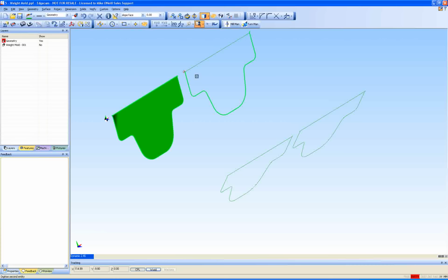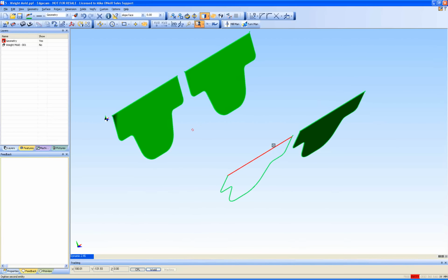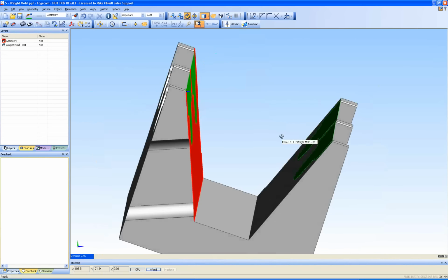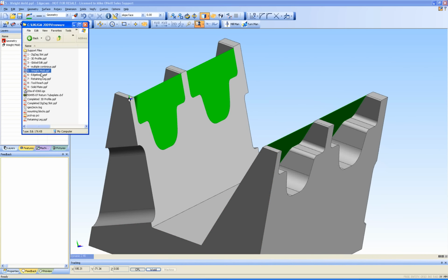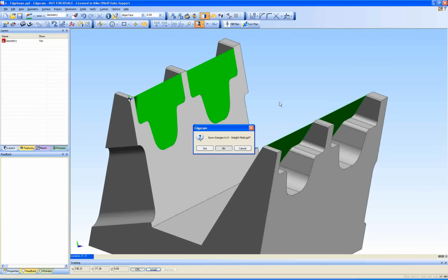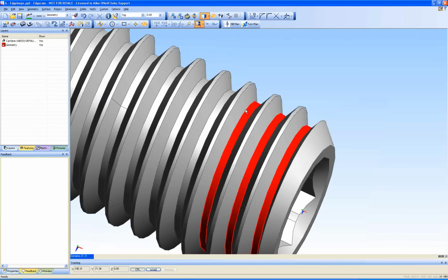So it's just a little bit of a time saving rule really. And then the ruled surface again doesn't have to be precisely accurate in this particular case, but it certainly is a perfect solution to box in the sides of that particular component in order to drive a cutter along. So again, a number of tips and tricks in there, supported also with the freeware function. Another item that is close to my heart is the making of an edge loop feature.